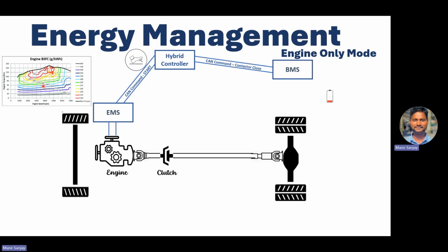Because here your vehicle is just taking, let's say, around 260 Newton meter of peak torque, but this BSFC says you can take more than that to bring your engine to the most efficient zone. That means you need to load your engine, but you don't need higher speed, right? You need to maintain that speed. Otherwise, the driver will feel discomfort, pressing 40% or 50% throttle and expecting the vehicle to run at XYZ speed, and the vehicle will run fast. So in that case, you need to load your engine to operate it in the most efficient zone.